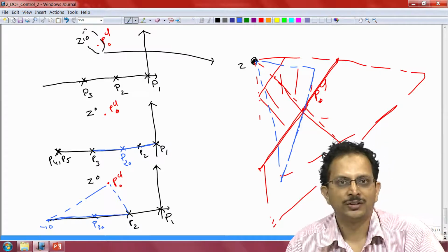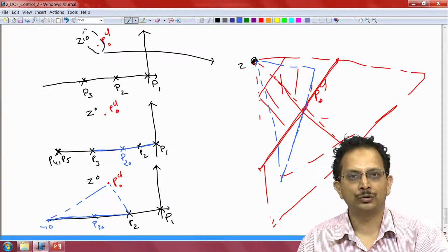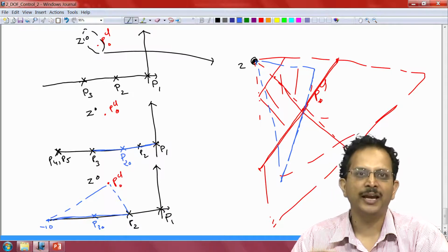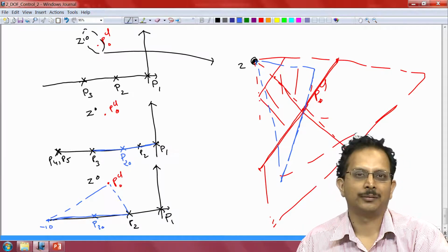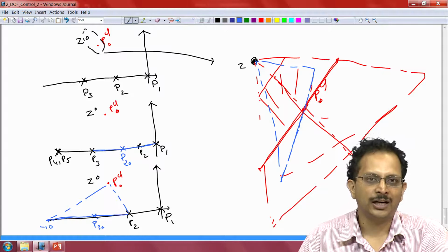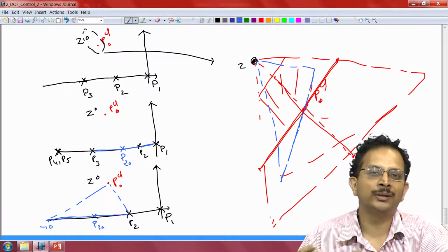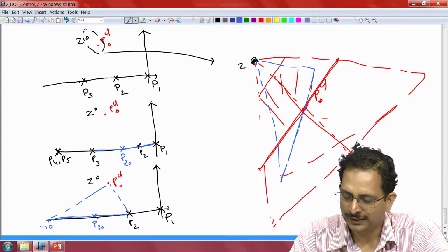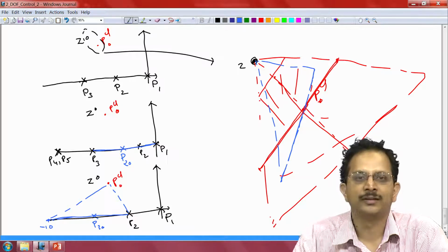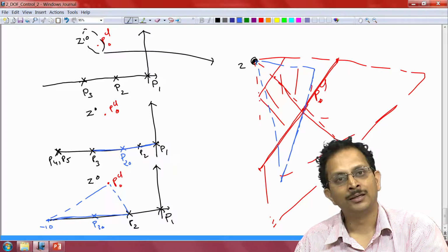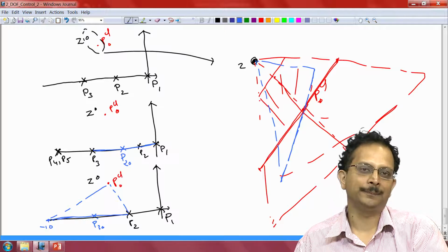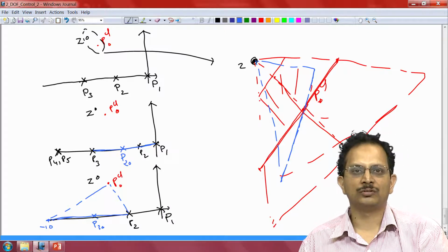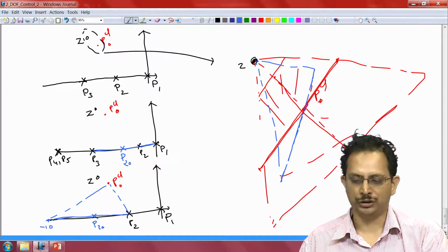Now, suppose we also had uncertainty associated with the gain of the plant. So, if the gain was lesser by a certain amount, so let us say the gain was at its minimum value of 0.3, then the closed loop pole would be located somewhere here when both the open loop poles of the plant are located at the nominal positions.